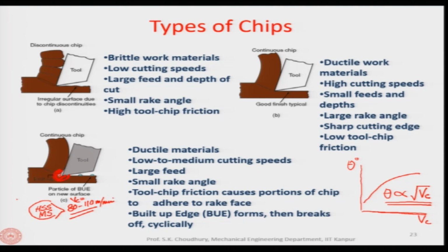It is harder than the tool material, and therefore the tool life will be high and the tool will not wear out, in rough turning where the cutting force and tool wear become very high. This is probably the only advantage, but otherwise the built up edge should, as far as possible, be avoided.